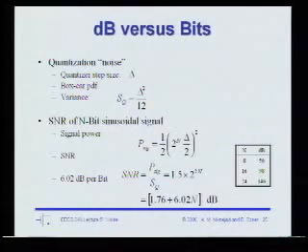And we can characterize that quantization effect with basically, if we assume that the quantization is uniform, then you can show that the SNR, the effective SNR of a quantization signal, goes like 1.76 plus 6.02 times the number of bits. So if you plug in like 8 bits in there, you get about 50 dB of SNR. So it's very useful to do the opposite. If you have an amplifier that has a certain SNR, it's very convenient to express what the effective number of bits are in that amplifier.